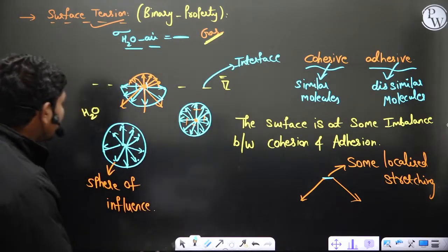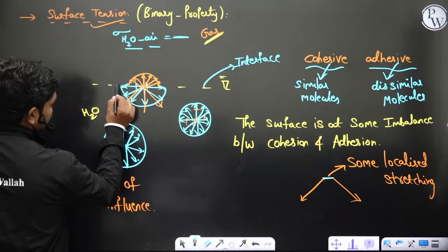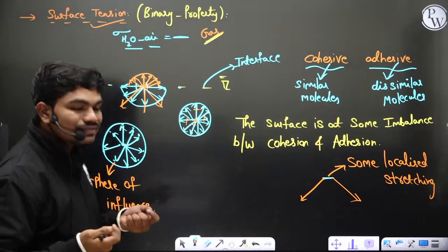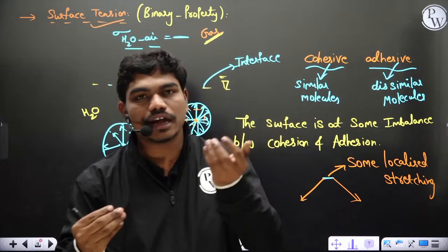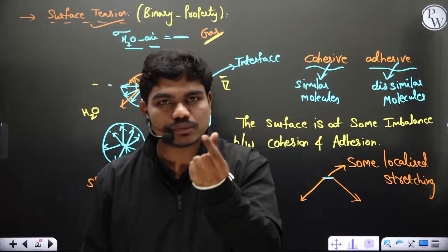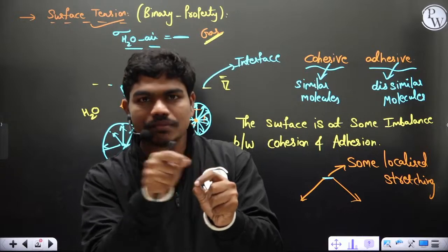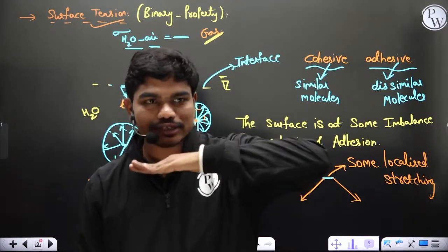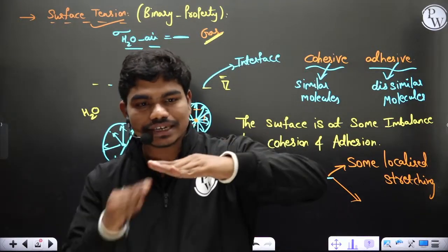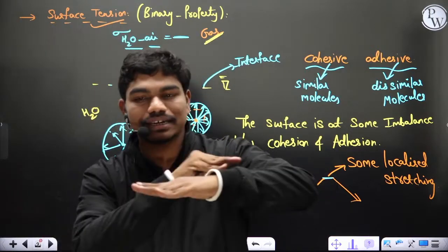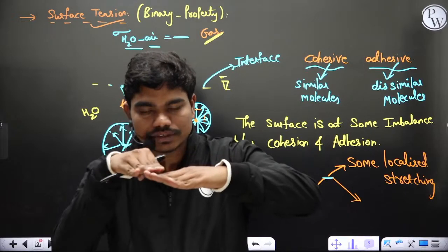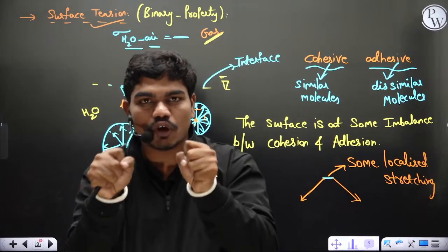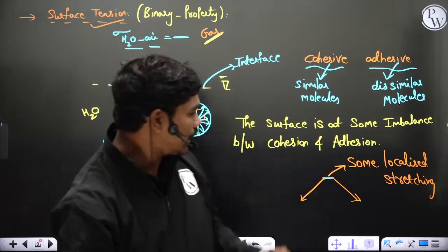Okay, if this is under surface tension, normally we say the interface is under tension. We cannot classify the interface as belonging to either fluid, like the definition of a boundary in thermodynamics. A boundary does not belong to the system or the surroundings. Similarly, whenever we talk about an interface, we don't say that the interface is either in gas or in liquid; it is an interface, an imaginary one. So at the level of the interface, definitely every molecule is locally subjected to stretching. And that's how this happens.